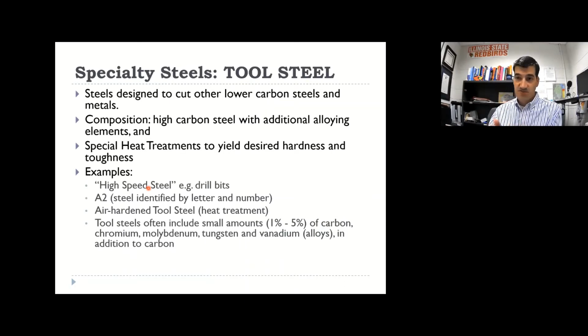That will make it strong and hard. And if it's hard, then you can sharpen it and it will hold an edge. And so that's what we use to make files and saw blades and things like that. You use a high carbon steel, oftentimes with a bunch of additives added into it. The carbon, obviously, you want a high carbon. Also things like chromium and molybdenum and tungsten, these things down here, vanadium also. So you add a bunch of alloy metals to it, and that tends to make it stronger.